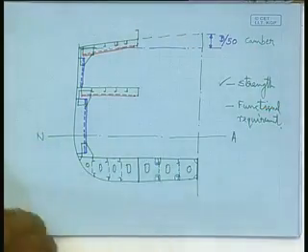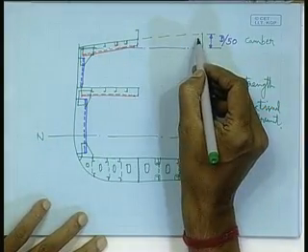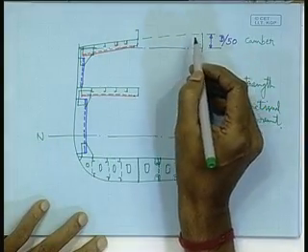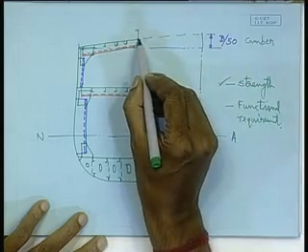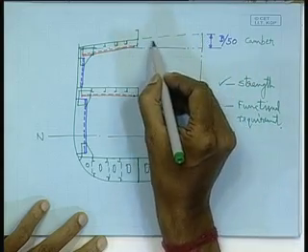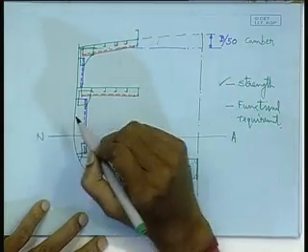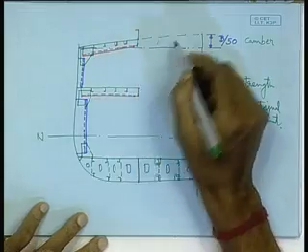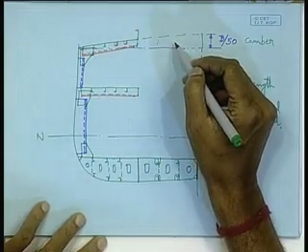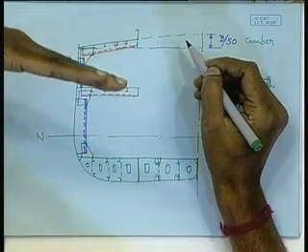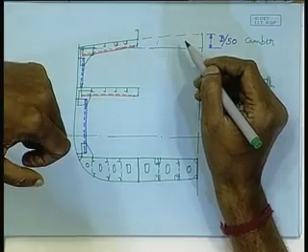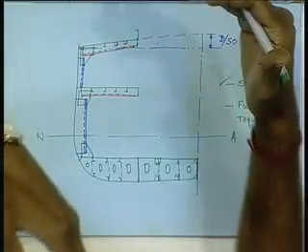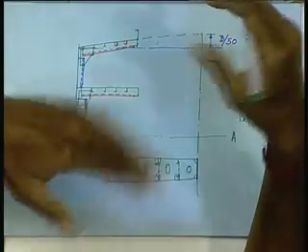So, through that we will calculate, and obviously that is calculated in way of the hatch opening, because where the hatch opening is not there, the plate is continuous, as well as you have so many additional longitudinals also, but you do not take that, because firstly the longitudinals may not be there, there can be transverses. We have talked about the cross deck structure, and that plate is small between the two hatch openings, so they are not contributing towards longitudinal strength.